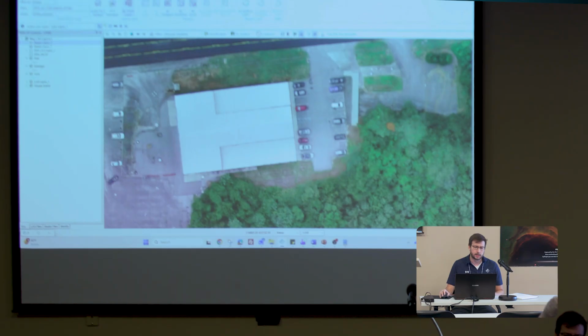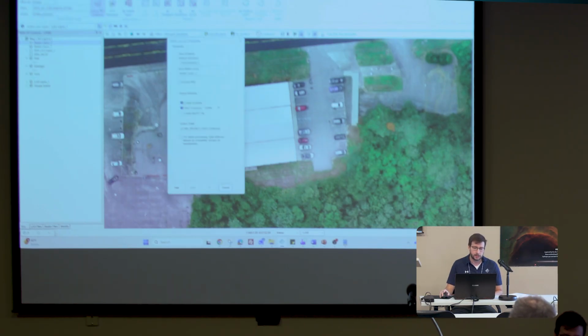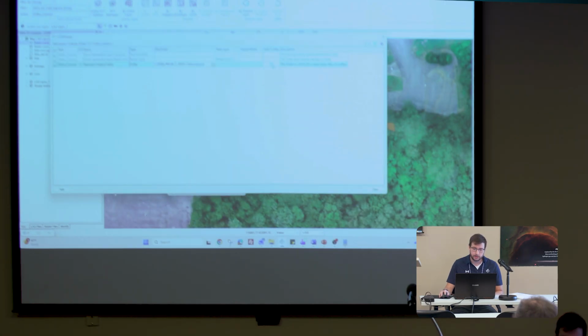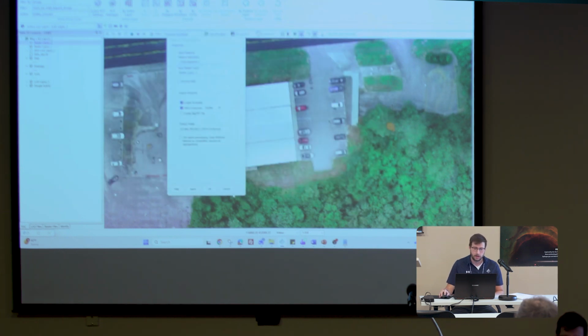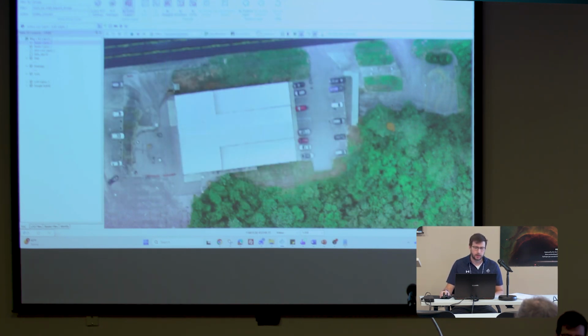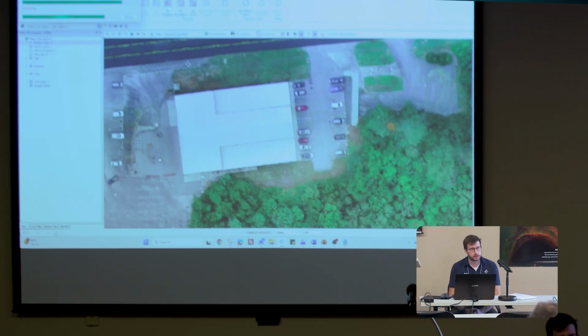So let's go to point task at the top, click on active PCT settings again, and change it to something like 20. Let's do a good bit more. We're still referencing our original raster layer. I'm going to change that to add to map this time. I forgot to set that. Let me know if I'm losing anybody. I'm clicking around kind of fast. I'm going to click OK and run that again and see what 20 does. Anytime we reduce that value, we're choosing to compress the file even more. The default setting is, I think, 90, so it's not as compressed.